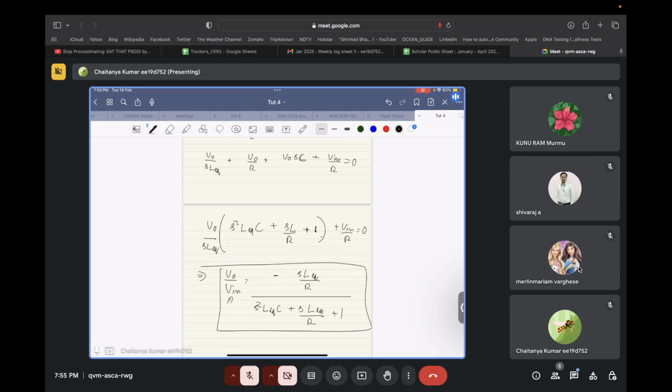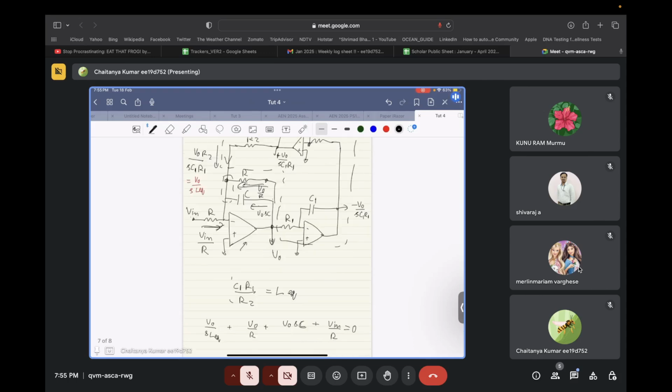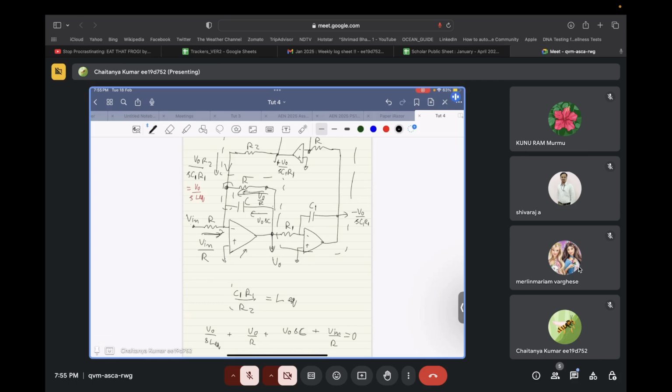In that case, the signal to noise ratio has actually become less than 1. That noise has become larger than the signal. And you have to deal with these kinds of problems when you are working with resistors or maybe transistors. But it so turns out that the energy storing elements, the capacitor or the inductor, are noiseless.